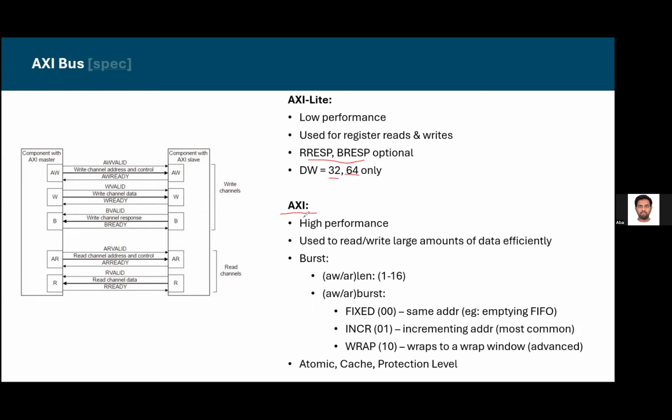Okay, so all of your requests will be in one clock, right? Everything is parallel. So now when you do that, what happens? Now you are only giving one address here. So this burst type tells the subordinate how to interpret this address. If you're asking for a fixed burst, if you set the burst to 0, 0, 0, it means you're asking for a fixed burst.